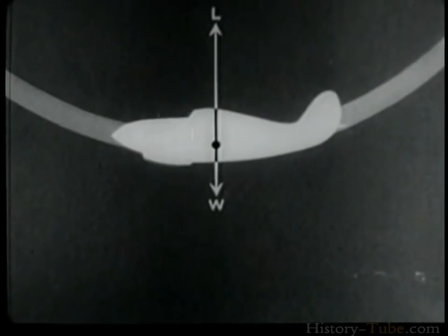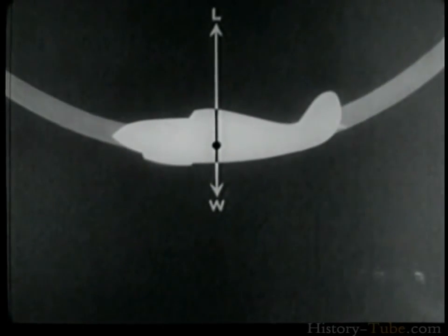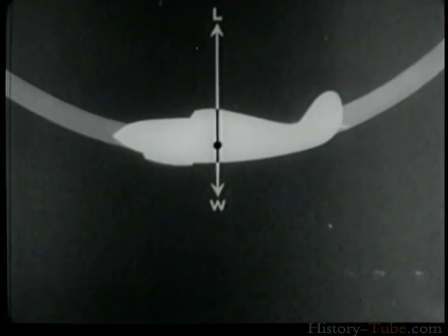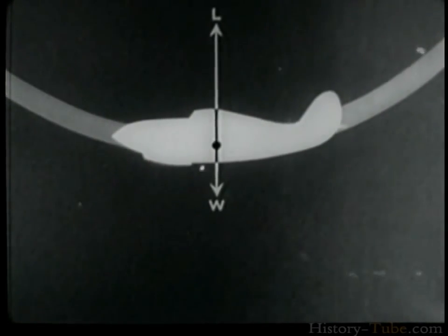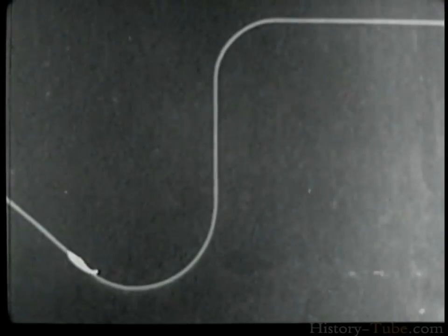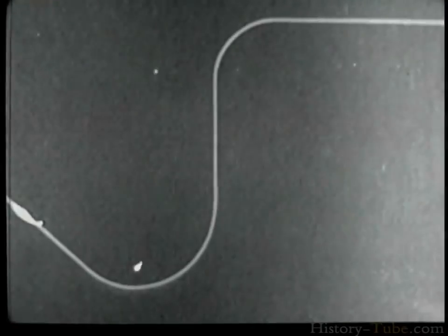In pulling out of the dive, the angle of attack must be increased slowly. During this maneuver, the lift may attain several times the value of the weight. This increase in lift produces acceleration, which in turn